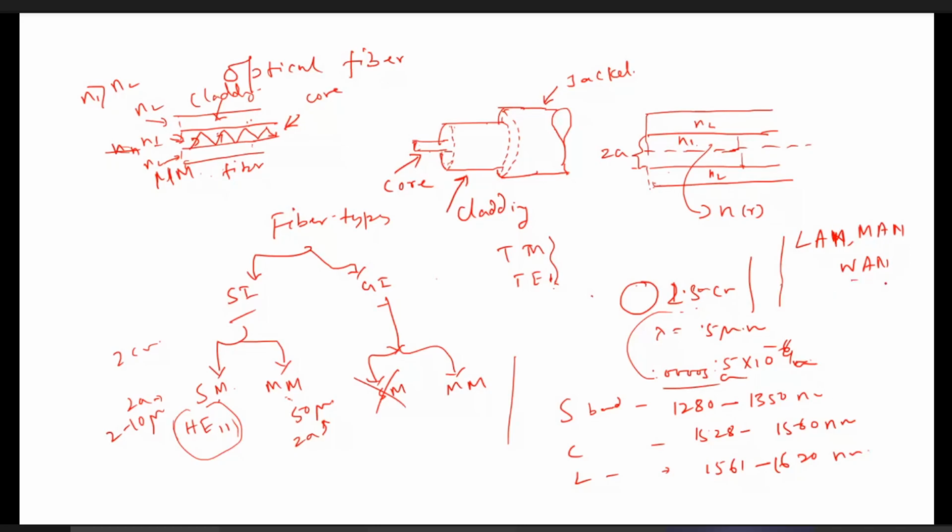Right. So very long distance communication systems and metropolitan areas can use it, and also it can support, theoretically it has huge channel capacity, but generally more than 60,000 speech signals can be transmitted through optical fibers. Nowadays, a huge bandwidth is available. If you consider WDM systems, to some extent we'll discuss it. WDM, DWDM system: wavelength division multiplexing, dense wavelength division multiplexing.